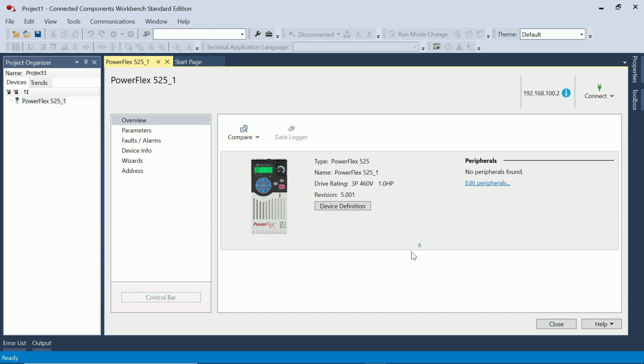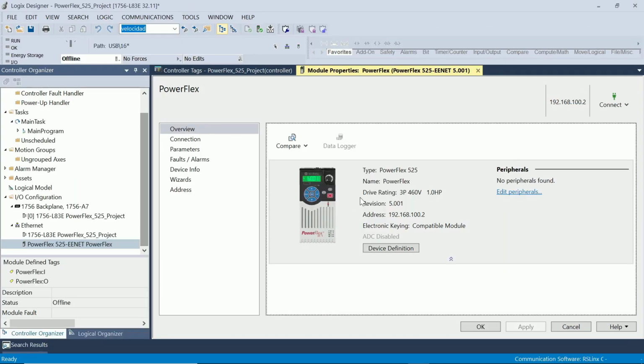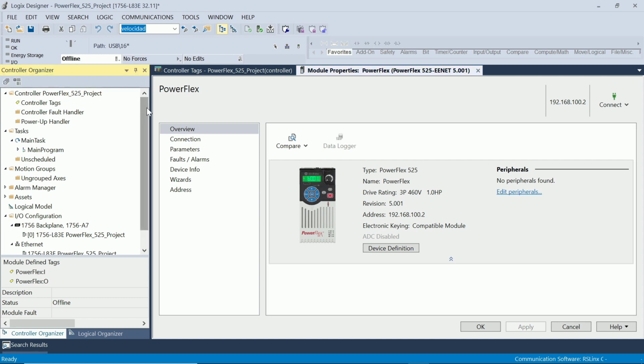Okay, so that's what Allen Bradley thought of, where they say, well, there should be a way which is quicker and easier so that we can load those parameters to any type of PowerFlex, just as long as it's the same model and it matches exactly for the same thing. So, since this information is actually stored in my PLC, what they said was, let's suppose that this drive is burnt out.